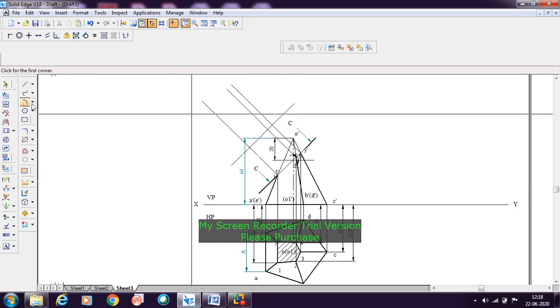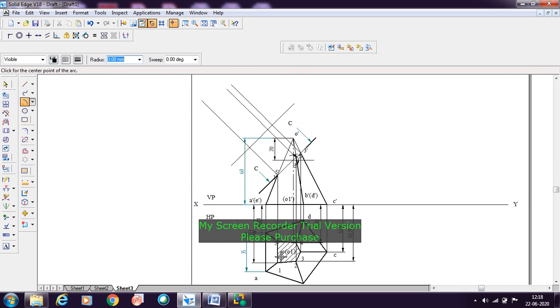So here it is. Go with the RP center here. So this is for the point number 1. For point number 1, you need to mark it here. In this case it is 52.3. Go with the RP center here. Take this point as center, and here is the distance, 52.3. By taking that you need to cut an arc here. Similarly for the point number 2, the distance is 50.74. From here it is 50.74, and then you need to cut an arc here.